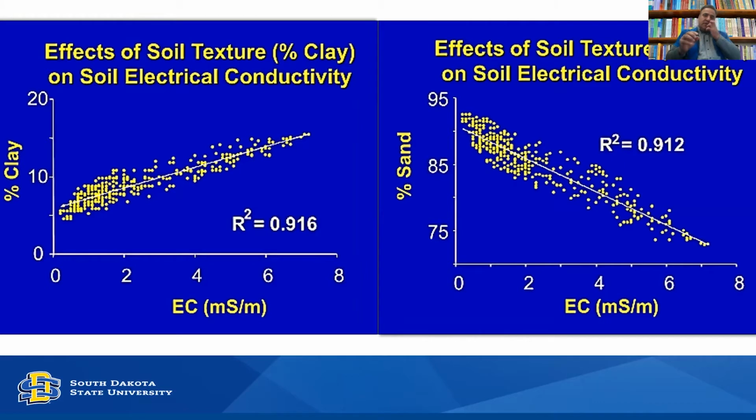It's not only because of finer or coarser particles, but also related to the electrolytes or salinity we have in clay. More salinity or electrolytes in clay soil can carry more electrons and have higher conductivity from point A to point B. And for sandy soil, it's obvious that because it washed out all the electrolytes, you will get lower electrical conductivity.